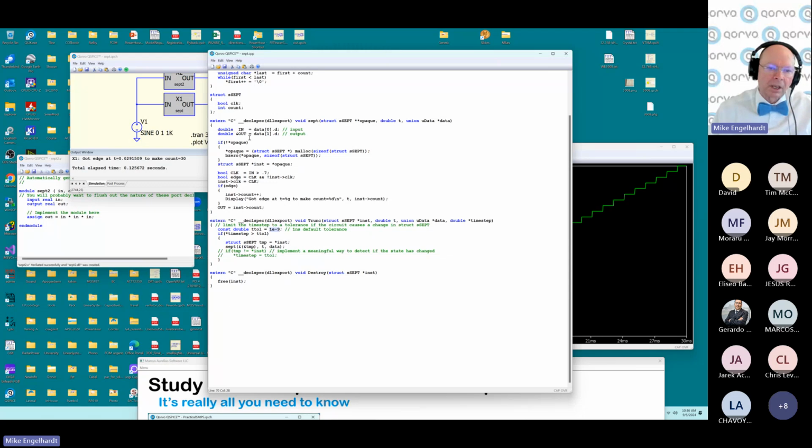It defaults to a nanosecond. You can make it anything you want. You want a picosecond, it'll all run just fine. And it says that if you're planning on taking a time step bigger than my tolerance, then I want you to think and maybe reduce that time step.